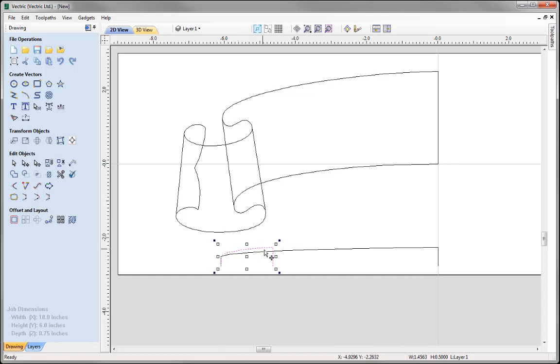At the moment I can see that cross section is coming well over our main fold that we've got here, so we need to bring that down. If we go into node edit mode, I'm going to take this node here and nudge that down quite a little bit so it's well underneath the first fold cross section that we have. And then I'm going to take this control handle and bring that down too, so we can start to see how the shape will flow.